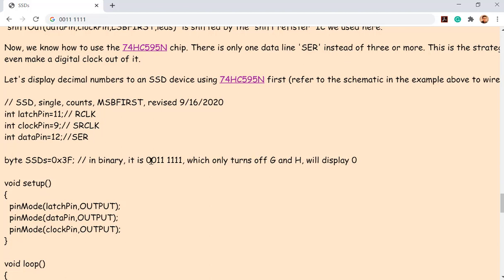So here's a shift register, right? You have a data line, and you have a clock, boom, boom, boom, boom, doing this. So everything is ready. Then boom. That's how that works. If you are doing MSB first, okay, 8 bits. What is this bit? What is this number here right now?